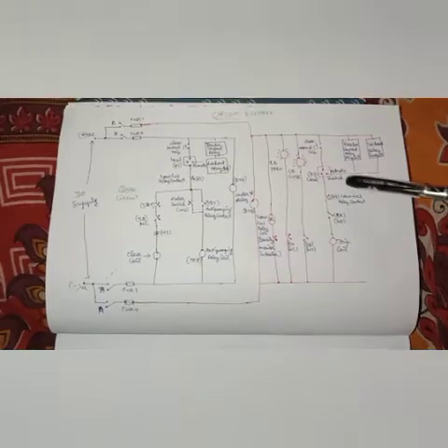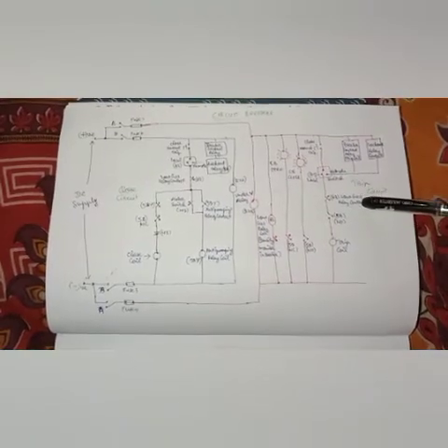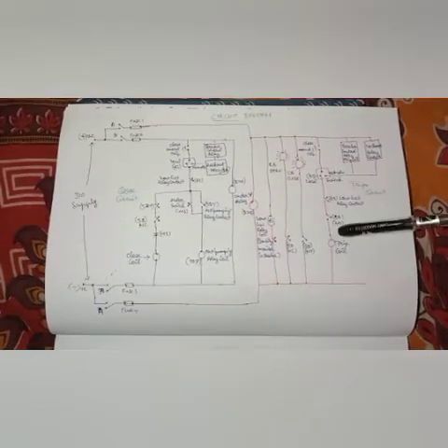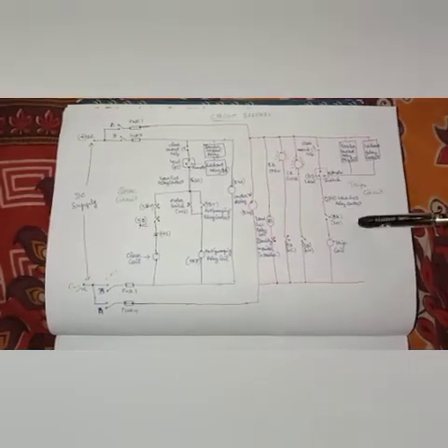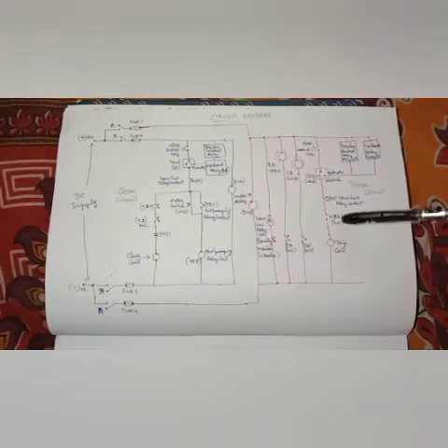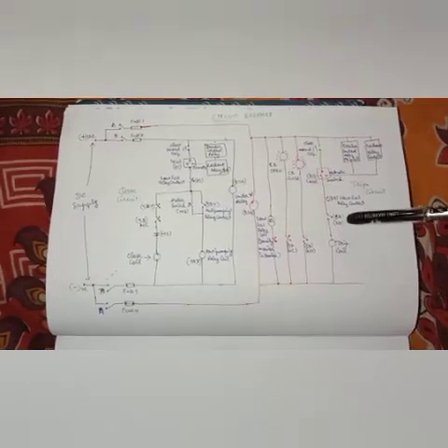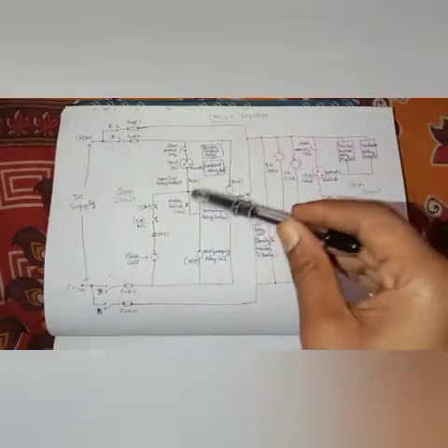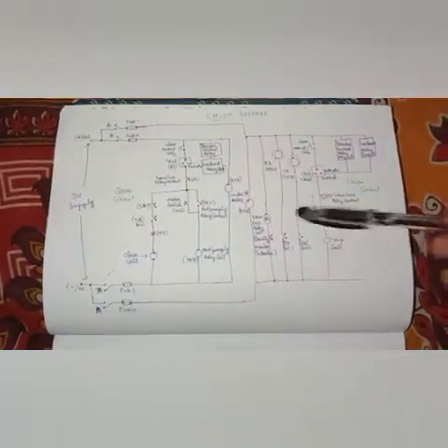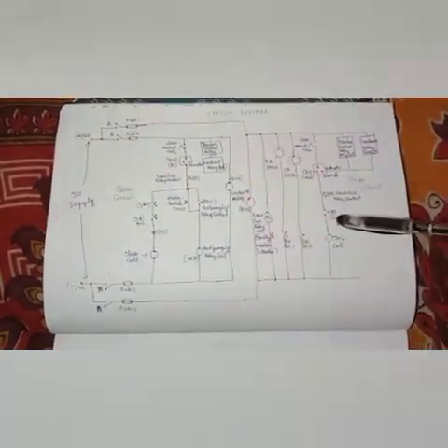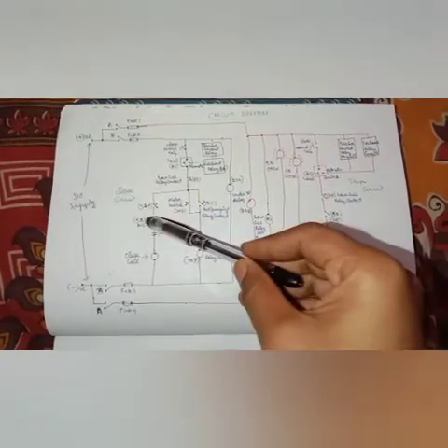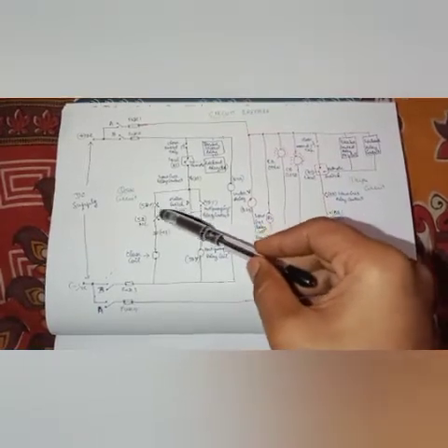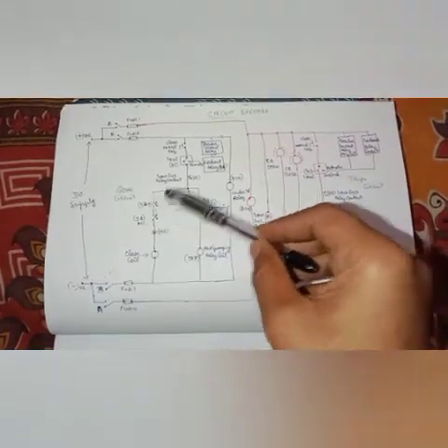And also coming up to the circuit, here the low gas relay is connected in series with the tripping coil circuits. Then the NO contact, NO in the sense normally open. So if the breaker is closed, I am now saying the operating condition, I have closed the breaker, in the sense this NC gets opened, and this anti-pumping relay will get opened.